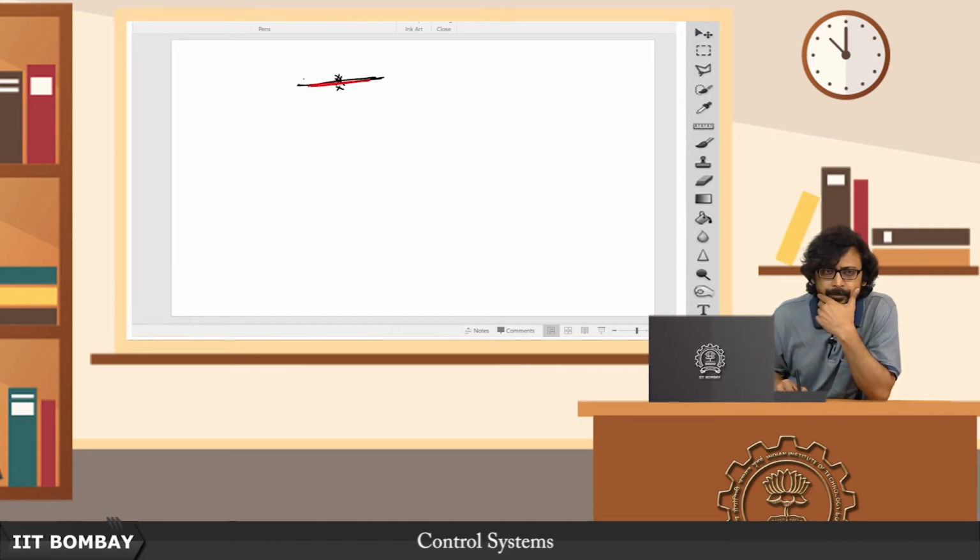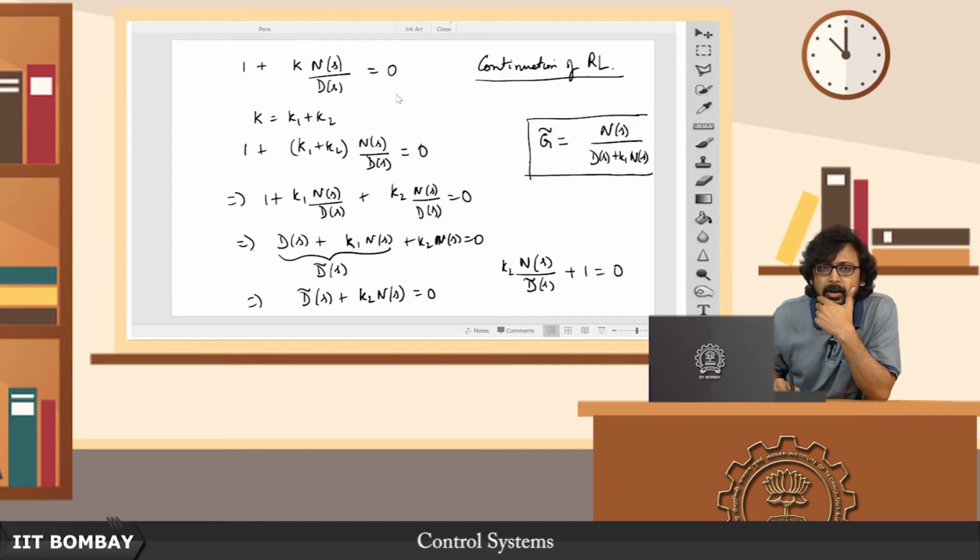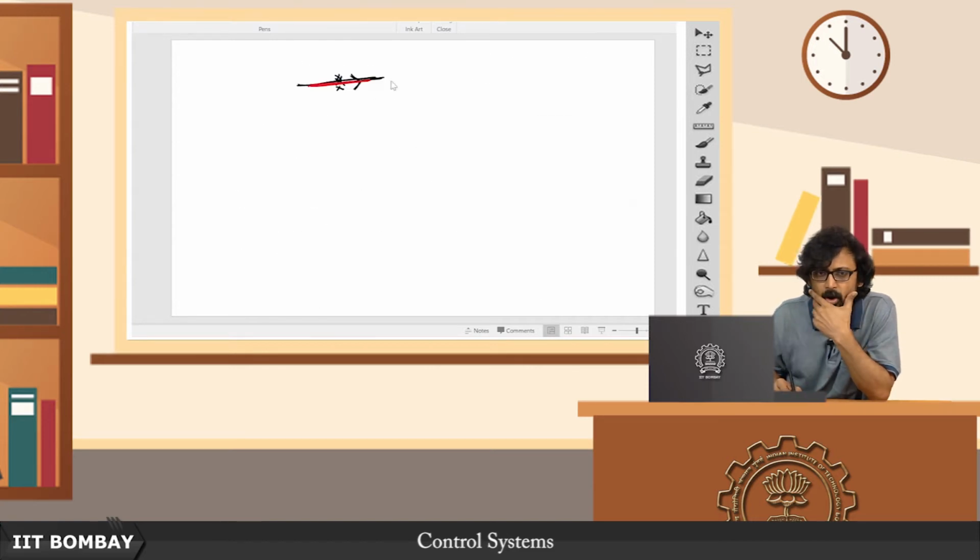So now if that is the case, then you know that one of the directions of departure is clearly this, and based on this angle of arrival and departure criteria application, we saw that the branches from this repeated set of roots will have to emerge separated by 2 pi by q radian angle.